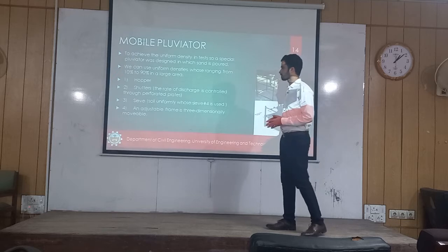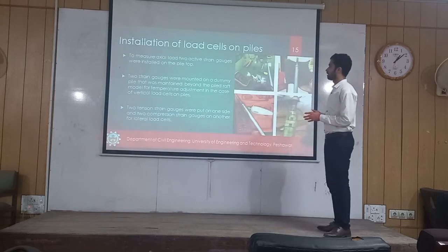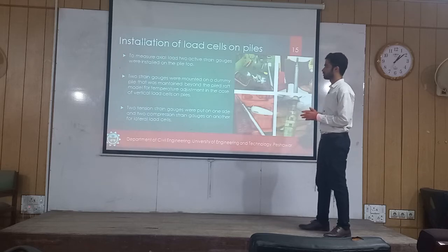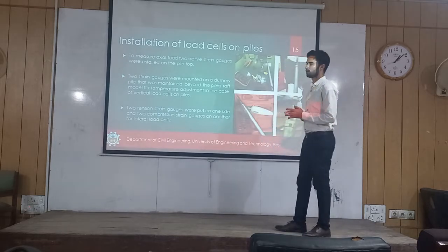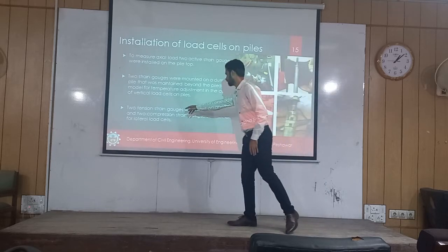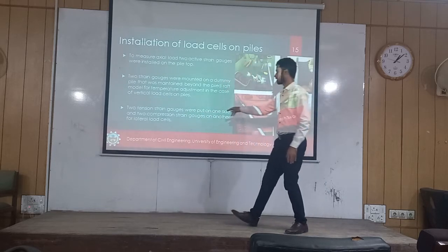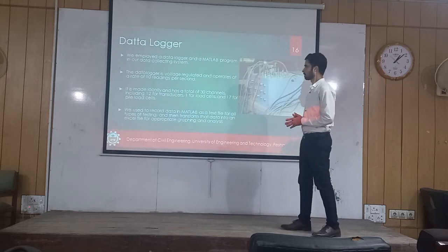Next, installation of load cells on piles. We installed load cells on piles to know the displacement of piles when the load is applied. Two strain gauges were mounted on a dummy pile for the temperature adjustment, and two tension strain gauges were put on one side and two compression strain gauges put on the other for the load cells.